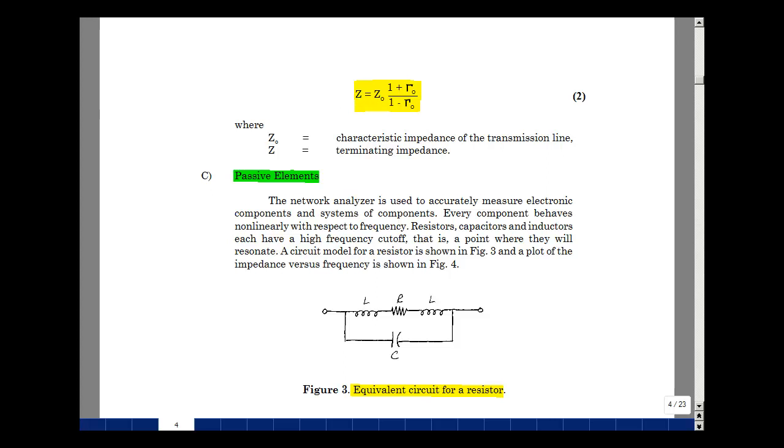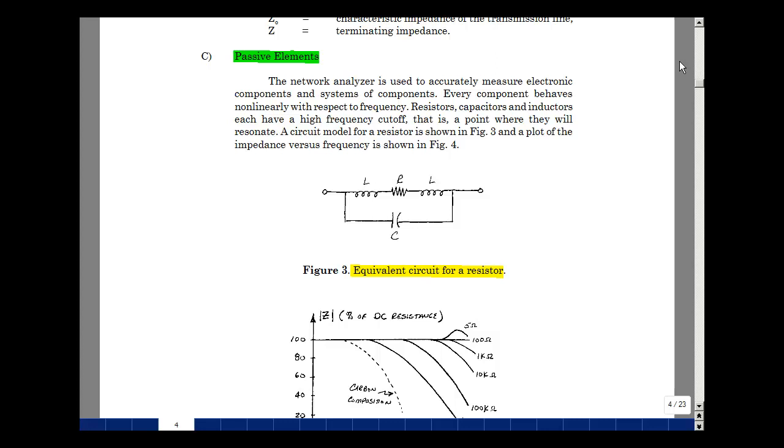The first one's going to be a resistor, and in the ebook lecture notes, in Chapter 1, there's a model for a resistor, which consists of an ideal resistance, inductance for the lead on the left side, and inductance for the lead on the right side. Now there is some resistance that's kind of lumped into the value of R. Usually R is much bigger than a few hundred milliohms, so basically just dominated by the resistance value. And then between the outer connections of the resistor, there's effectively some capacitance.